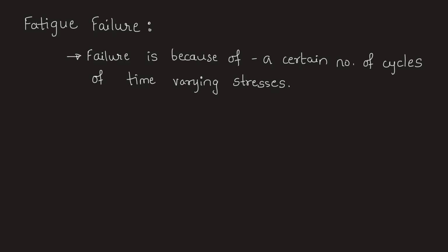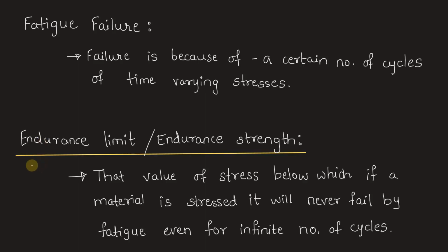In this context, we have the term endurance limit, or endurance strength, or fatigue strength. These are three different terms used to denote the same thing. So endurance limit indicates that value of stress below which, if a material is stressed, it will never fail by fatigue, even for an infinite number of cycles.